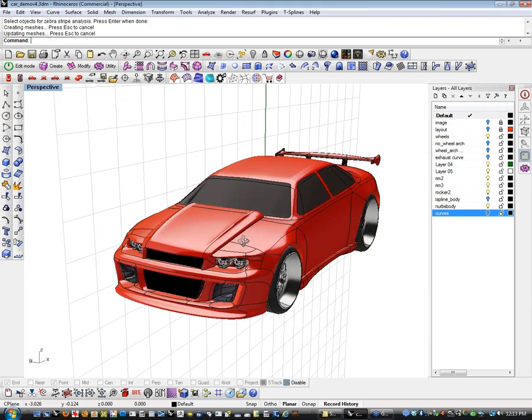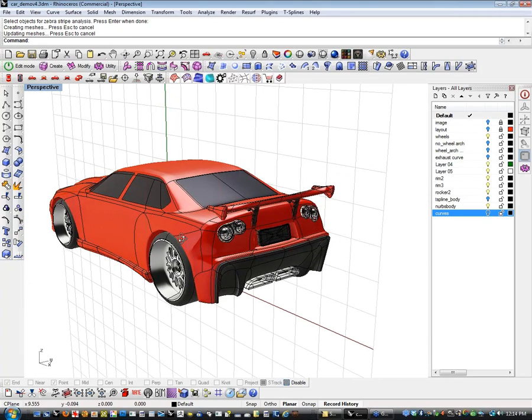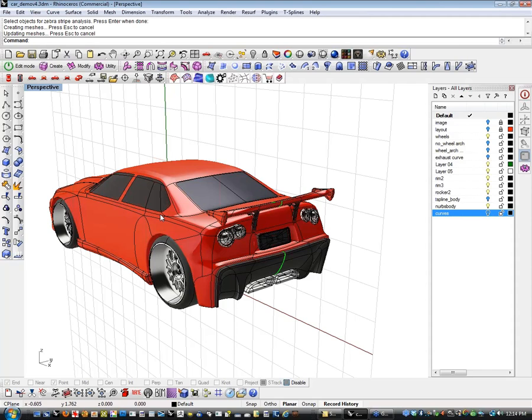With the T-Splines workflow, one of the coolest things about that is first of all, you're doing kind of the same thing. You're laying out big, broad patches, and you're knitting them together. The cool thing is, once you knit them together, they're one unified surface. And so if you make a modification to, say, a primary surface, your transitionary surfaces, all your blend surfaces, update as a seamless part of the complete model. So essentially, it's like grabbing a big chunk of clay and moving the clay around, and all the transitions happen with you. So a modification in T-Splines is a situation where you're grabbing it and you're moving it around, and you're making a modification that's taking minutes, as opposed to tearing apart a NURBS model, which can take days.